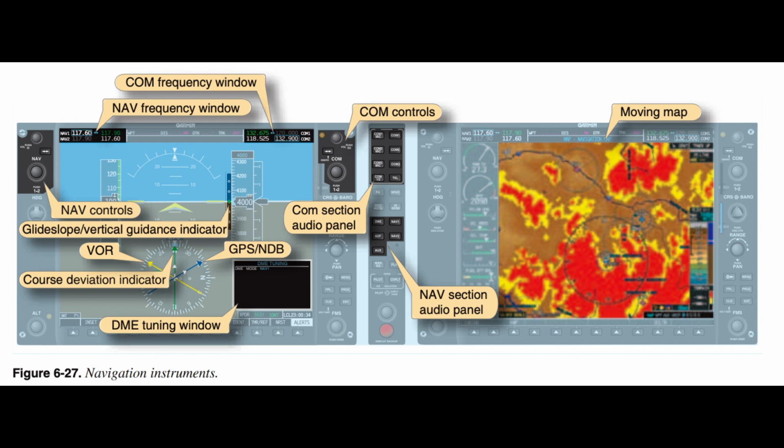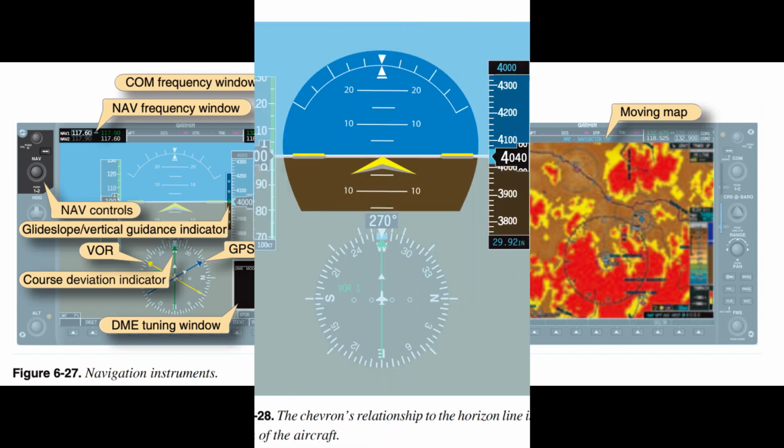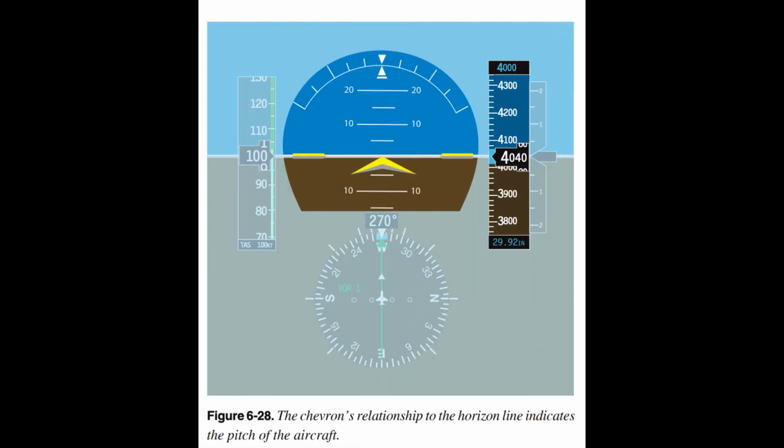In attitude instrument flight, the four-step process is used to control pitch attitude, bank attitude, and power application of the aircraft. The EFD displays indications precisely enough that a pilot can apply control more accurately. Pitch control. The pitch control is indicated on the attitude indicator, which spans the full width of the PFD. Due to the increased size of the display, minute changes in pitch can be made and corrected.